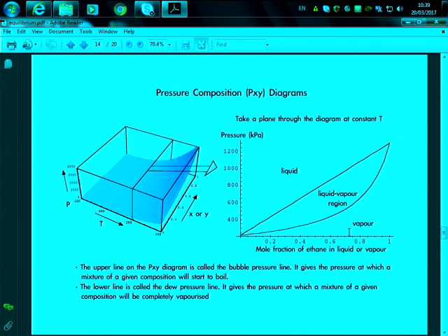If you have a pipeline where you have a delta pressure decreasing, then again you will have to observe, for example, if you want to maintain the pipeline as a liquid flow, then you don't want to go to lower pressures that will generate a multi-phase flow and perhaps damage your pump if you have a pump that only handles liquids.